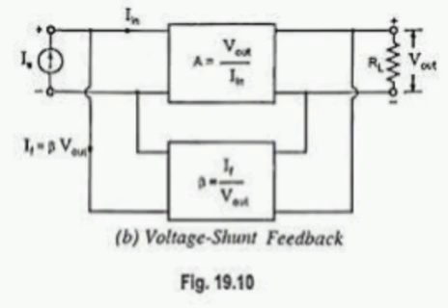Once again, voltage shunt topology: transresistance amplifier, output is shunt, input is shunt. Current shunt topology: current amplifier, output is series, input is shunt. Beta has no unit, it stabilizes the current gain of the amplifier. Example: cascading amplifier.